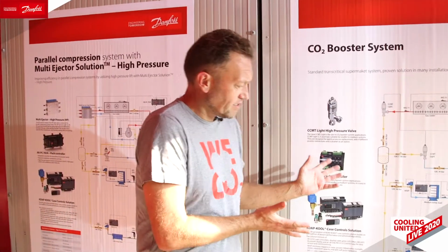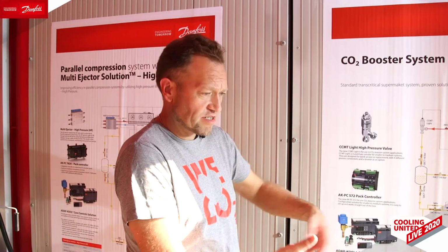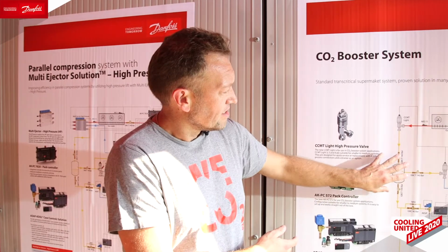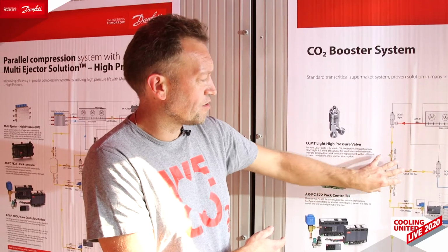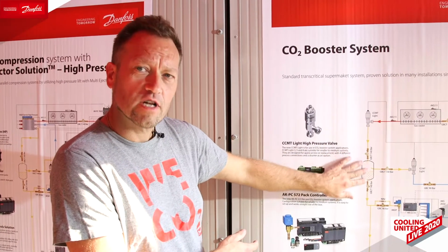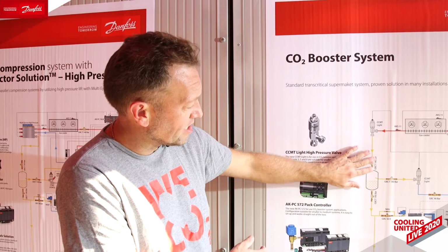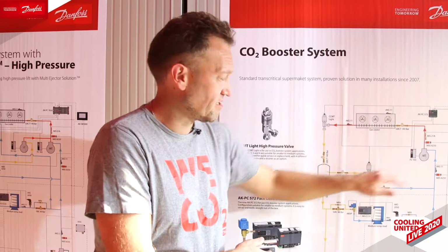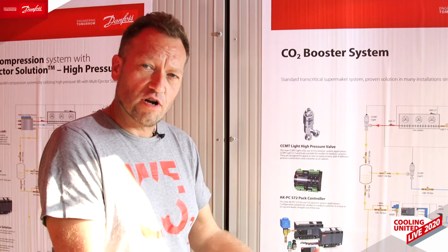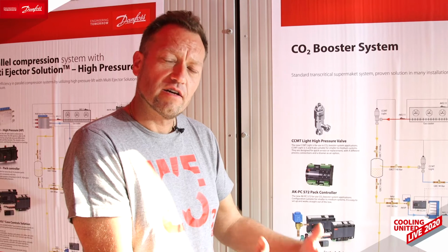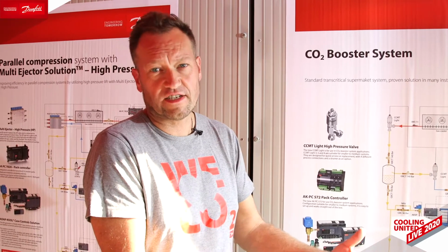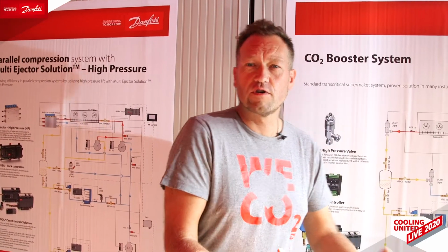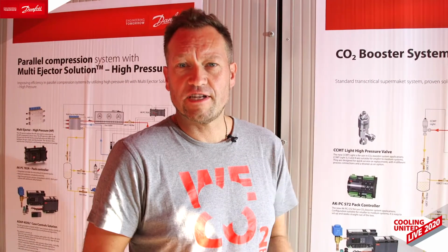One of the challenges with CO2 systems, and this is where we see the technology has evolved over time, is that this system is most efficient in colder climates when you have a high quality of the refrigerant, meaning that you produce little gas that has to be led back to the MT compressors. And this is where the next technologies come into place, like the parallel compressors and also the Danfoss multi-ejectors. But that will be the topic of the next introductions that we do here during the day. So back to you for now, Anja.